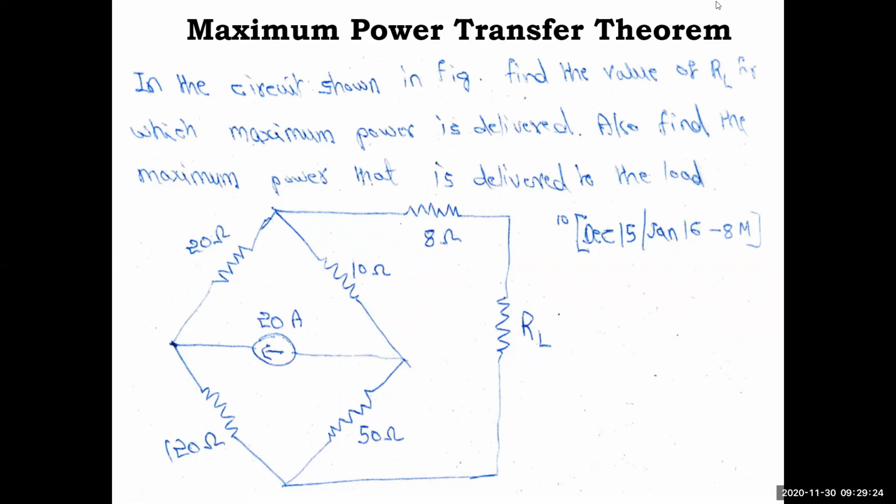In such cases, as we told in the very first video, we consider this as circuit B, as we have done in Thevenin's theorem. We'll consider this as circuit B and remove it first. Whatever you have here, we may name the terminals, since it is not given. We call these open terminals, maybe you can name them A and B. And this side I call circuit A.